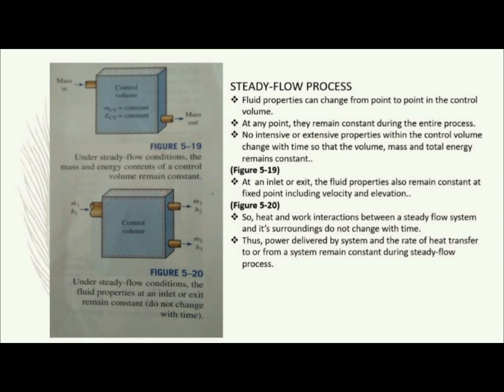At inlet or exit, the fluid properties also remain constant at fixed points, including velocity and elevation. For the example, you can refer to figure 5.20. So, heat and work interaction between a steady flow system and its surroundings do not change with time. Thus, power delivered by the system and the rate of heat transfer to or from a system remain constant during a steady flow process.